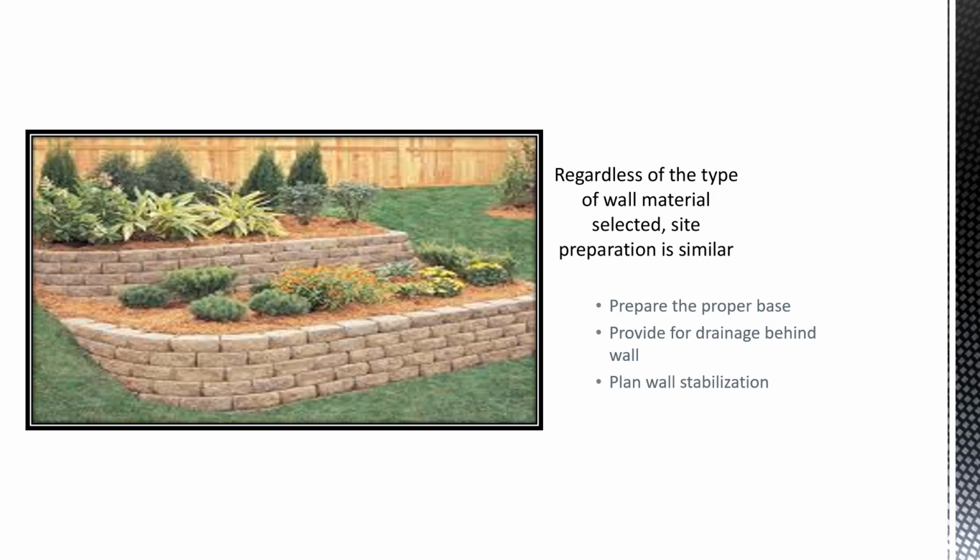But I've seen guys with walls over 4 feet not putting pipe behind the wall. I've seen them not putting gravel behind the wall. What are they doing? And so it blows my mind that there are individuals out there that are doing this every single day. But plan for wall stabilization, guys, and a big part of that is getting the drainage out from behind it. We've seen the horror stories.